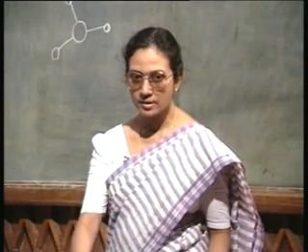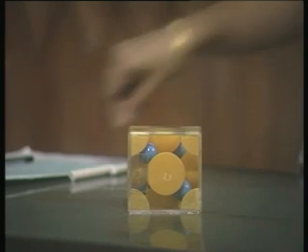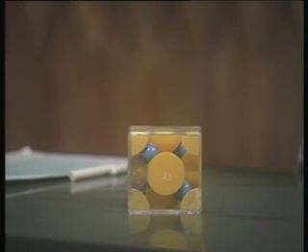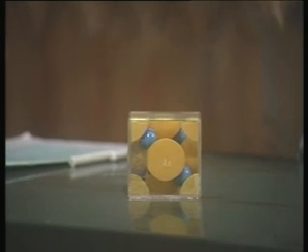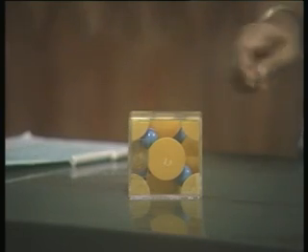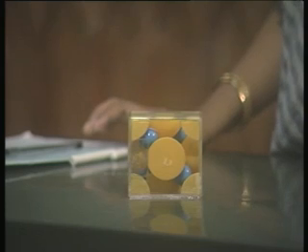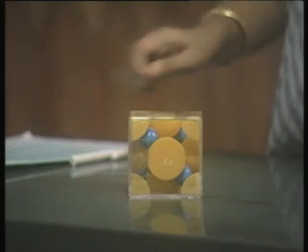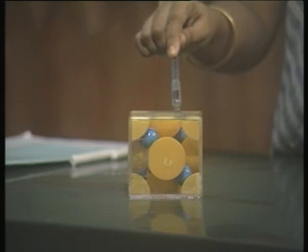If we look at this crystal, the first empty space you will notice is right inside, which should have been the site for a body centered atom. That space is empty here, right at the center with the coordinates half, half and half. Similarly, I have other empty spaces. For example, you see this blue atom of the second sublattice.